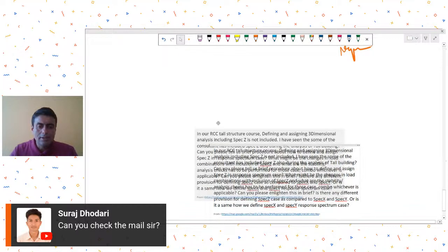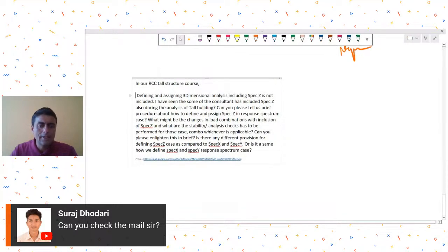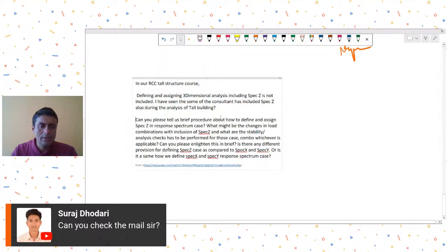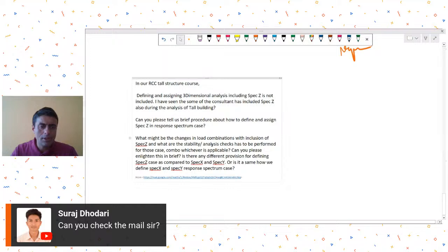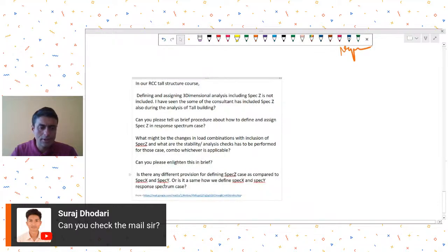He's saying, in our RCC tall structure course, defining and assigning three-dimensional spec Z, response spectrum in vertical direction is not included. I have seen some of the consultants have included spec Z also during the analysis of tall building. Can you please tell us how to define and assign spec Z in response spectrum case? What might be the changes in load combinations with inclusion of spec Z, and what are the stability analysis checks that have to be performed for those cases? Can you please enlighten this in brief? Is there any different provision for defining spec Z, or is it the same?